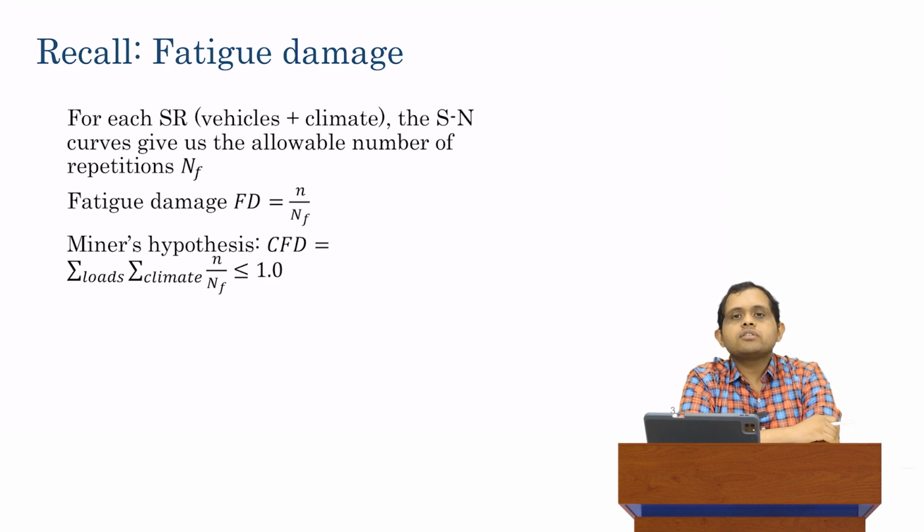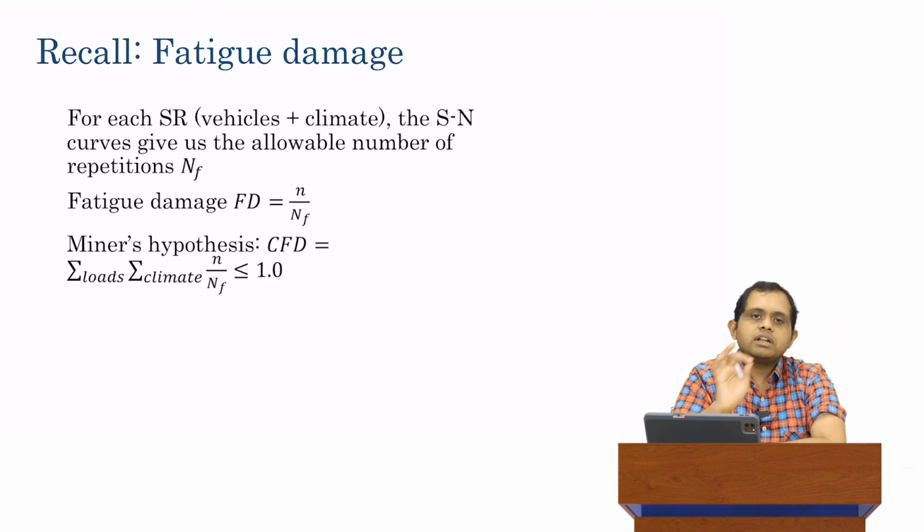So instead, we introduce the concept of fatigue theory, where the idea is that each load application has a very, very small stress. So the stress ratio is relatively small. It's less than 1. It's much less than 1. When you have this small amount of stress applied, you don't have any large amount of cracking developing, but you have a lot of micro cracks developing. So you have small cracks which are developing throughout the material. Over time, as you apply these small loads hundreds of thousands or millions of times, those small cracks start coalescing together and form a large crack. And that's then the final crack that we observe in terms of transverse cracking or longitudinal cracking.